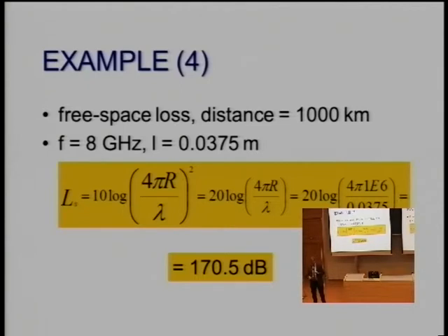Unfortunately, what does not compensate are propagation effects. The higher the frequency, the more pronounced the attenuation due to the atmosphere will be, and this is a function of rain. In clear weather, it doesn't matter. But if we have rain, then we are penalized at the very high frequencies.